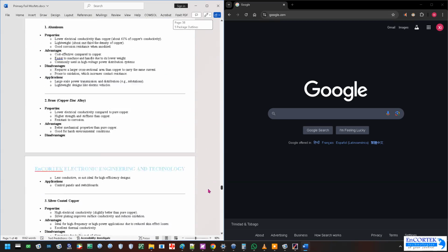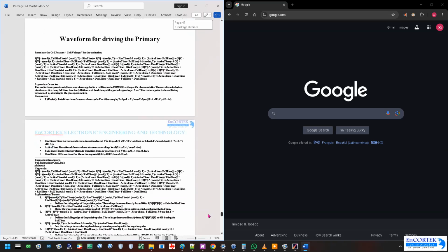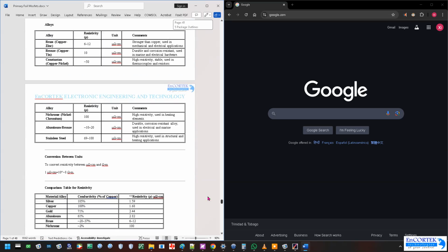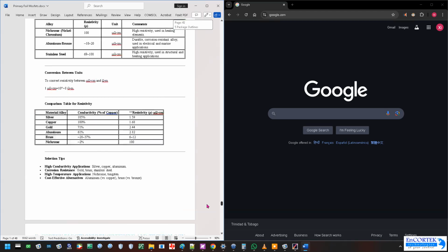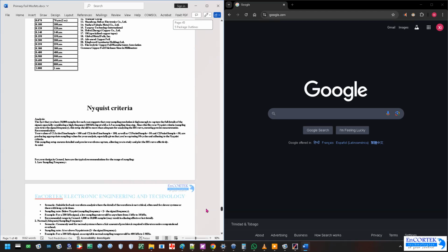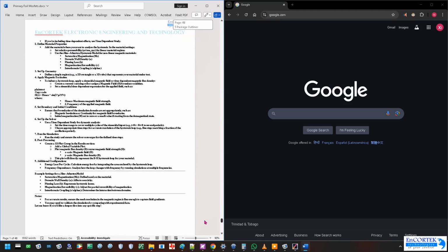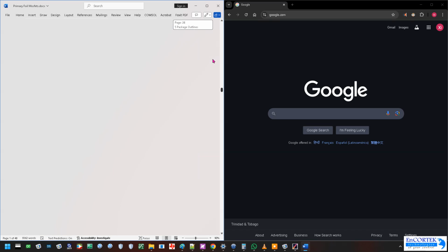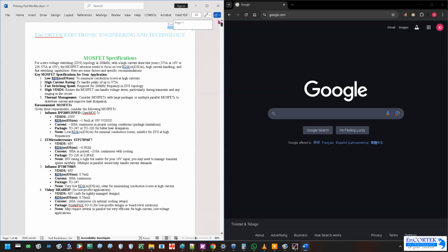It's a lot of documentation that has been going on, right? It's lots of data and equations. So anyway, what we're looking for here is a MOSFET with a very low ohmage. This one is 1.9 milliohms.